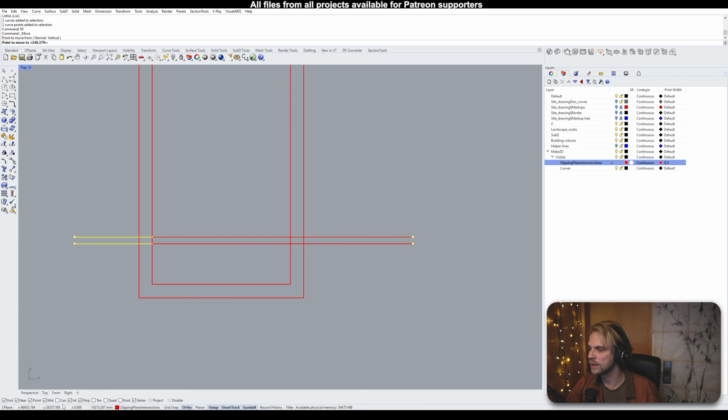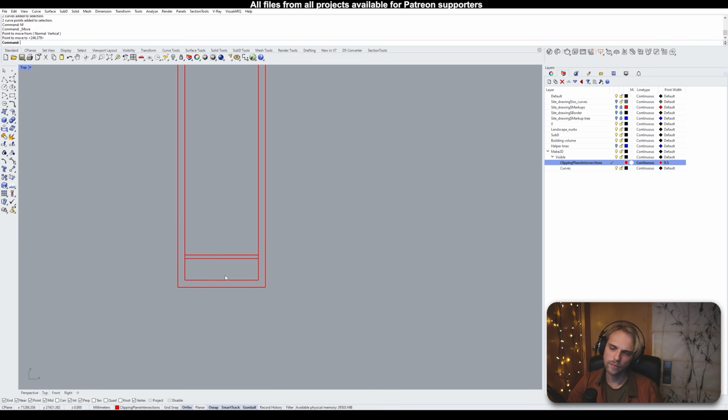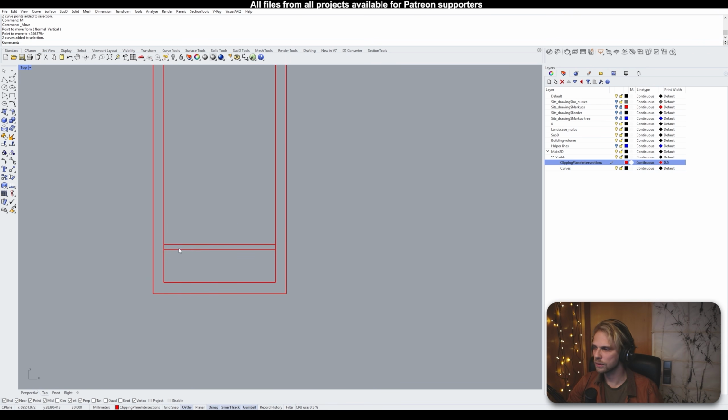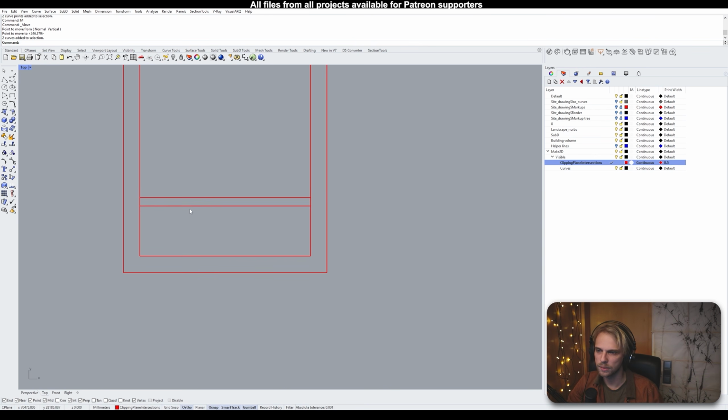Basically, you don't want the center snap because that gets annoying really fast, and tangent and quad snaps are only useful when you're dealing with circles, so usually I have those turned off. Everything else you should probably have turned on. Either way, we have ourselves a small little wall here, right?